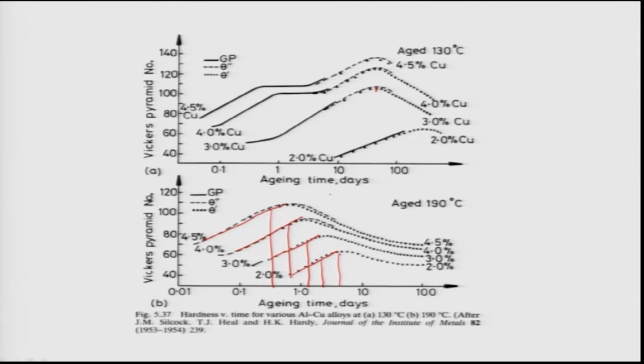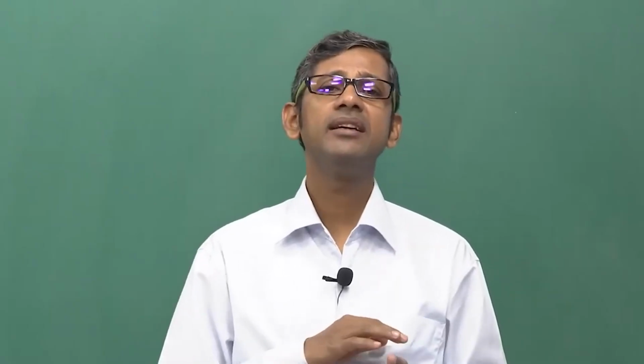There are other things which you should also remember. You have to understand that these precipitates are forming, or nucleating, on the grain boundaries or on the internal dislocations present near the grain boundaries as well as within the grains. So, we can improve the aging efficiency, or the ability of the alloy to age very nicely, by adopting two different approaches. One, which is very routinely done, is that after solution treatment followed by quenching, the alloy can be given a plastic deformation, which is simply rolling it or giving a forging treatment.